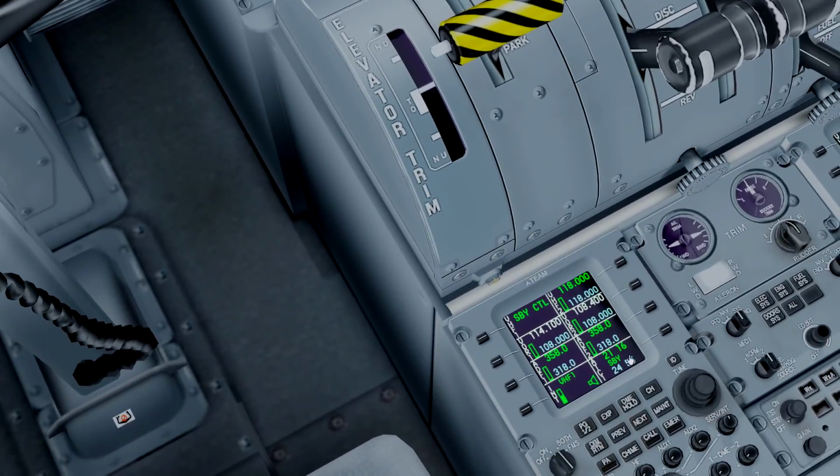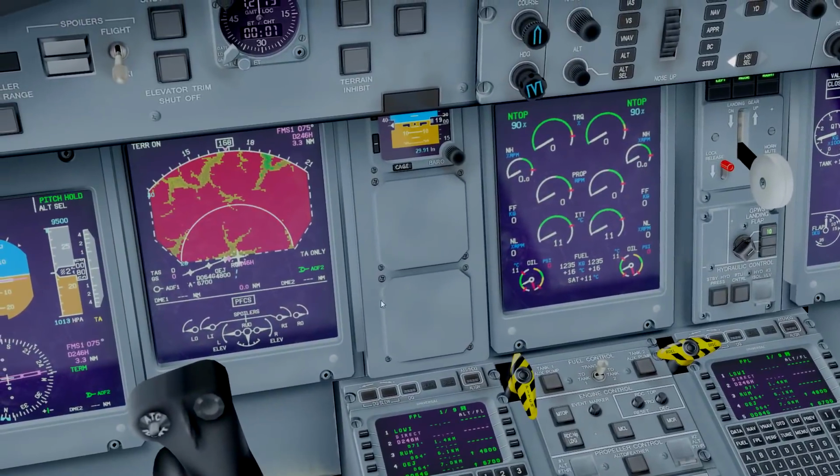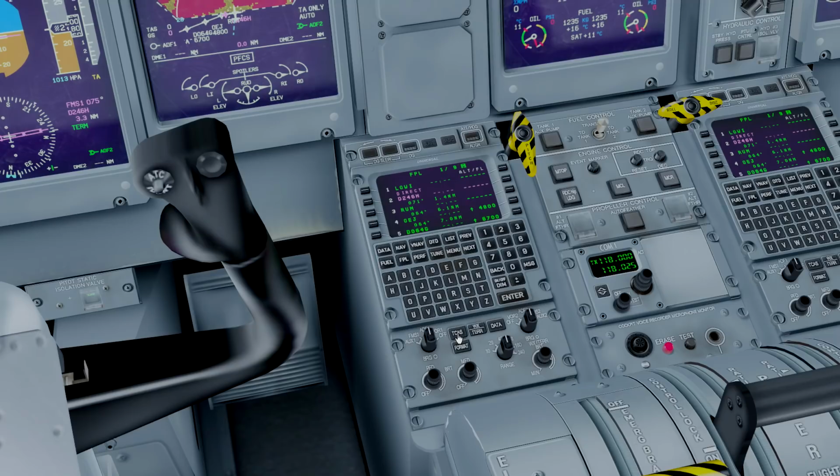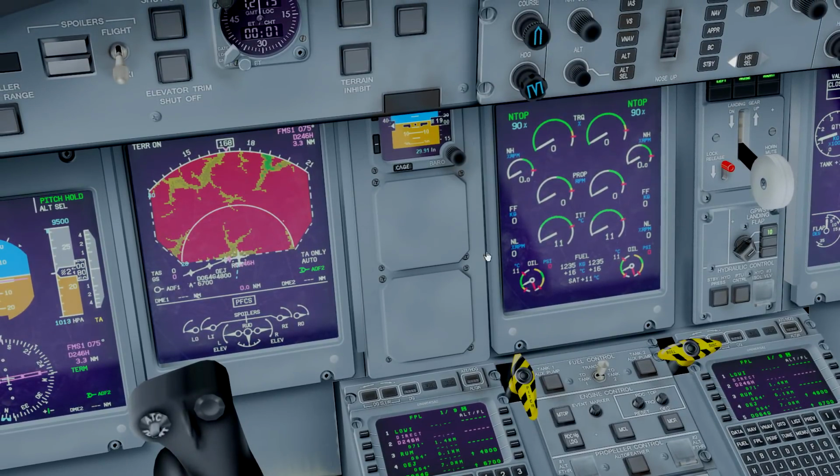Okay. So of course now you can just adjust this panel to your liking, maybe tune some ILS frequencies in the background as well. For example, here you can also set a squawk code if you want to. And if you want to put the TCAS on, you hold the button right here next to the transponder for 2 seconds, and it will turn on the TCAS. So as you can see right now, the TCAS should be on as soon as you depart.